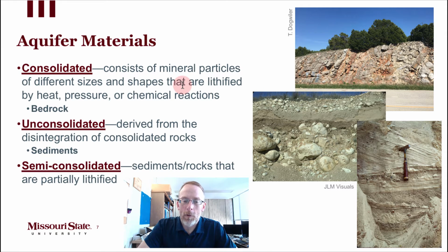Unconsolidated aquifers are loose sediments, so sands or gravels. In northern Missouri and the upper Midwest, there's a lot of deposits from the glaciers that occurred in the last ice age. Those deposits are not lithified. The sediment particles are not cemented together. They're just loose sands and gravels buried within the earth, so they're very good aquifers because there's no cement taking up space in them, and some of them are very coarse materials like gravels. They can hold a lot of water and they have a high permeability. So that makes them a good aquifer, because remember, a good aquifer means that it can deliver water for human consumption in a useful quantity.